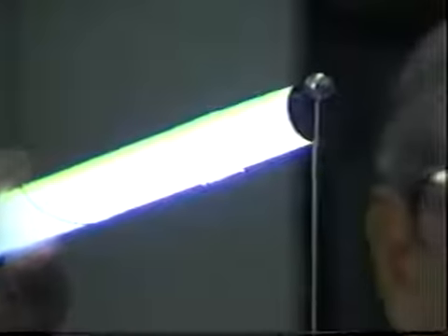I want to point out that in your vertical antenna, or like I told you in any antenna, the top of the antenna is always a voltage loop. The same thing, if I go back to the current loop, the same lamp will not light. Don't forget, this is a bar of stainless steel metal. When I put this at the voltage portion of the antenna, the standing waves in here are such that we get the current loop at the bottom where we can light the incandescent lamp, and the top of the antenna is a voltage loop where we can light our fluorescent lamp.